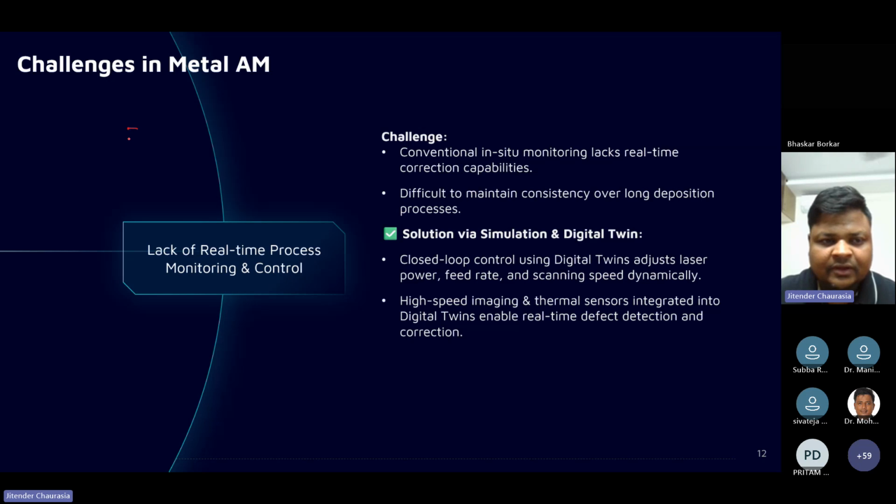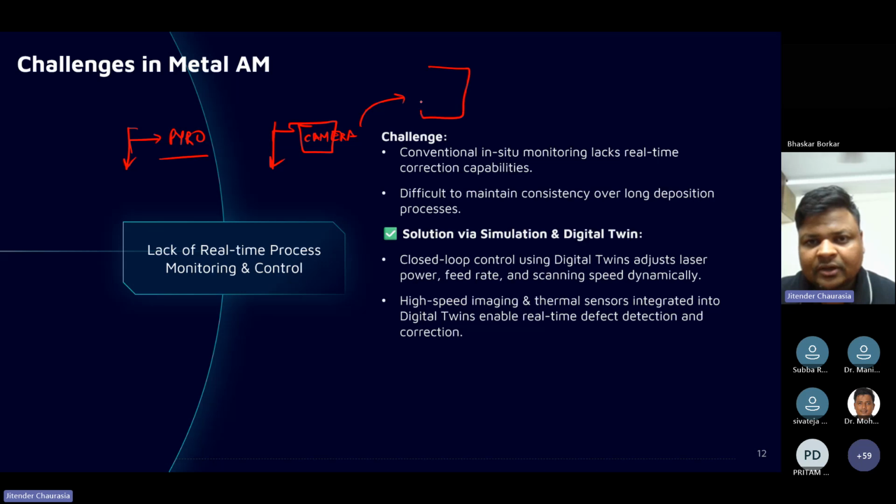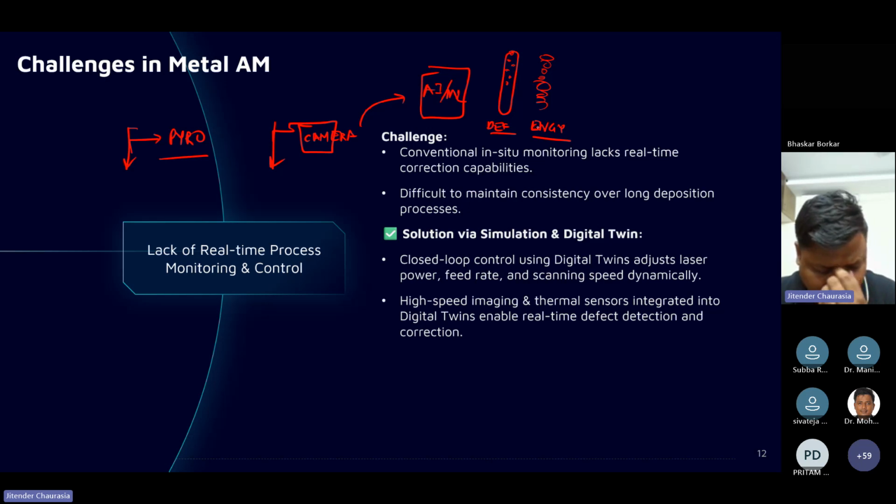One example I have given you is having a laser and then looking at the value through a pyrometer. Another example could be having a laser and, in real time, a camera here, just an optical CMOS camera. I should have trained some AIML model here with a lot of images. I will tell if somebody is depositing a track like this and it has some holes, it's a defective part. If it's a discontinuous deposit, big, small like this, I can say energy is not sufficient. I can give so many images of how insufficient energy will look. So this is camera based.